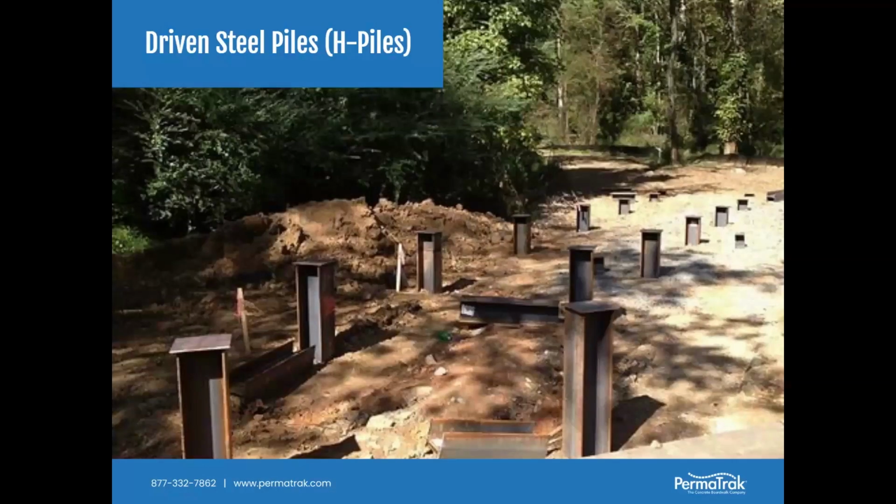And you might say, well, why in the world was it used here on this particular project? In this particular example, it was used because of the large thick layer of poor soil, and they needed something that could be driven through that layer down to a hard layer that was, in this case, about 40 feet below the ground level that you're seeing there. Sometimes it's the only option that can go that far.